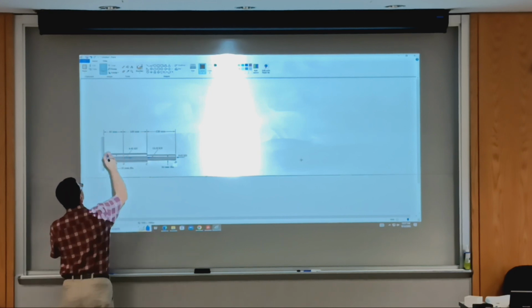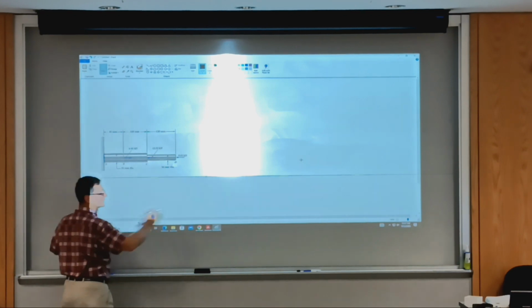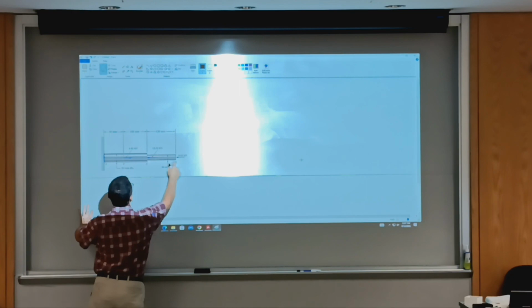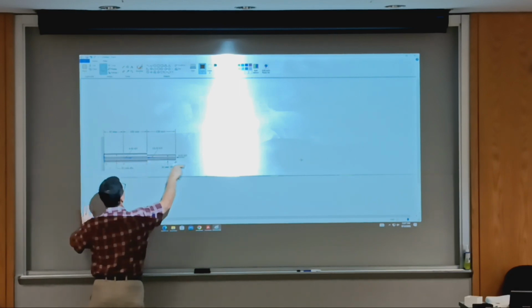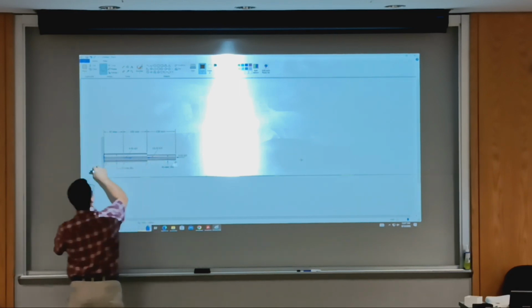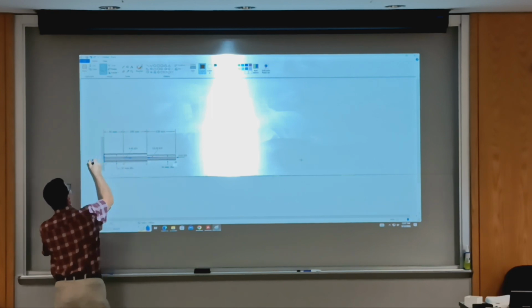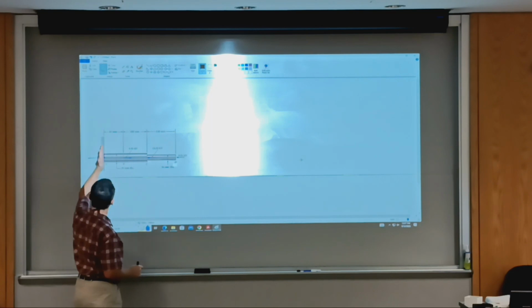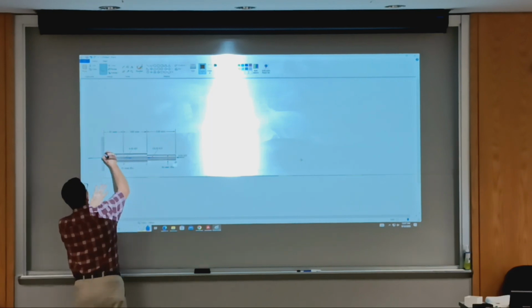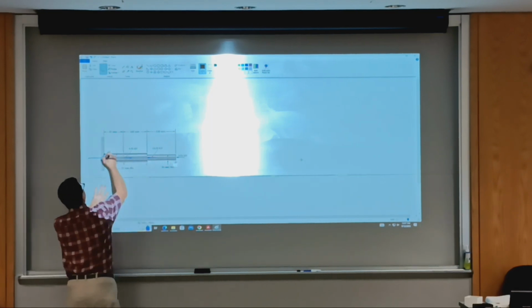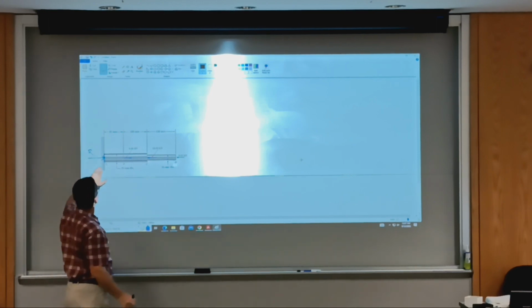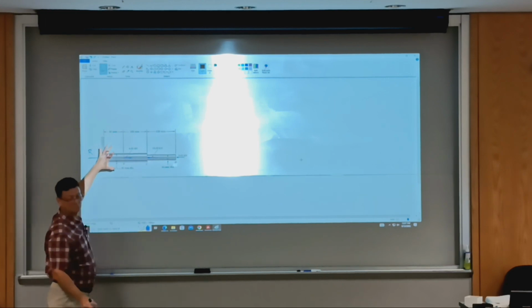Anyway, so we're going to do a free body diagram of just the column. So imagine this removed. I could go on paint and delete the ground. So you start looking. Some forces are one way, the other one or two towards the support, one away. We can assume that there's a net compression of the support. That is, you have a bearing stress here. You don't pull, say it's a welding. So this is a reaction at the support. This is a fixed end.